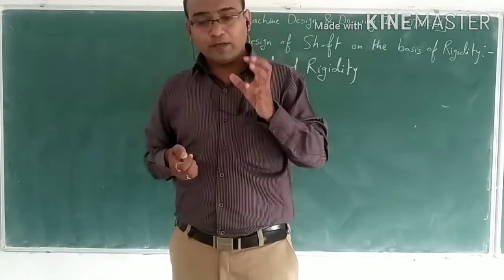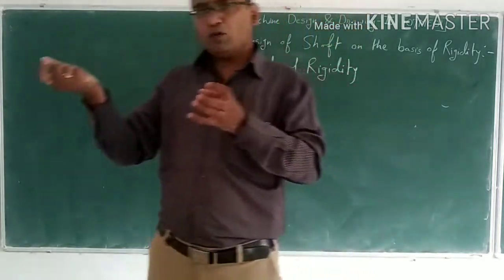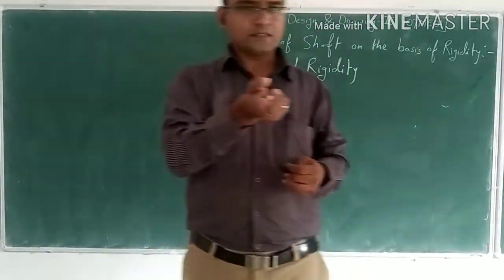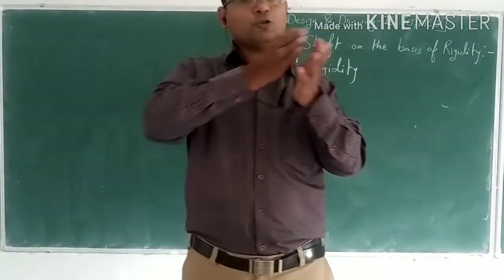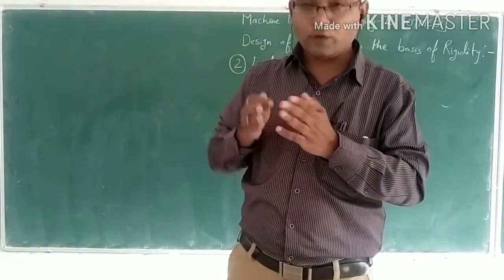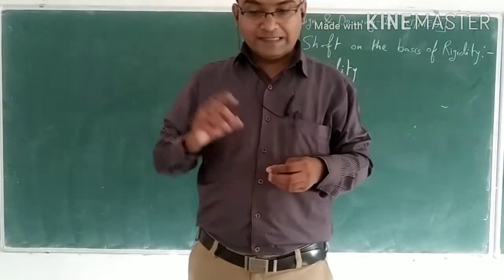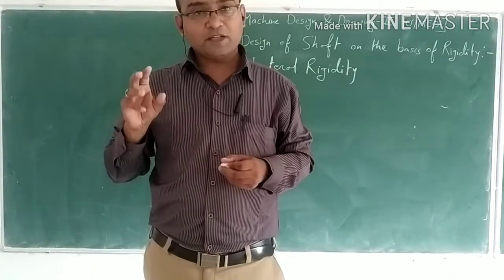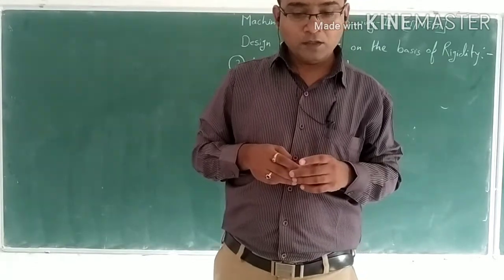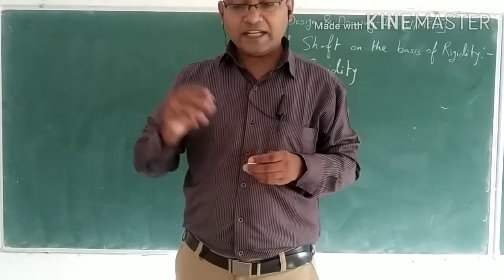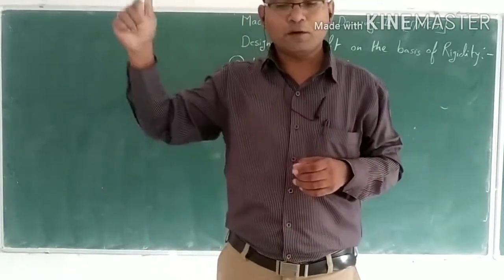But when the shaft is of variable cross section, maybe sometimes very small diameter, sometimes medium diameter, and sometimes a huge diameter, it depends on the variable cross sectional area. Then the lateral deflection may be determined from the fundamental equation for the elastic curve of a beam.